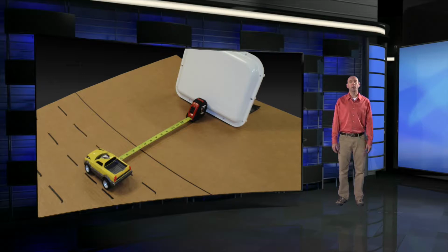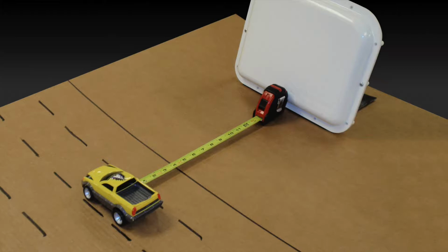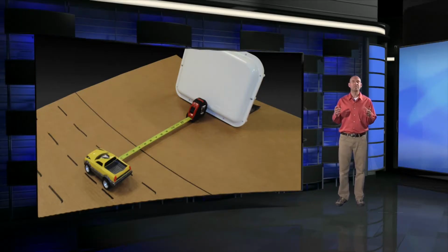So the next type of radar that I wanted to talk about is side-fire ranging radar. And side-fire ranging radar operates on the principle of measuring the distance from the sensor itself to the traffic on the roadway, as illustrated here. And this principle of measuring the distance to the vehicles is useful in generating the traffic statistics such as counts and occupancy and classifications for each individual lane. As a vehicle passes in front of the sensor, because it knows the distance, it knows the lane that that vehicle is traveling in, and is able to accumulate the statistics for that lane. SmartSensor HD is a good example of this type of a sensor.